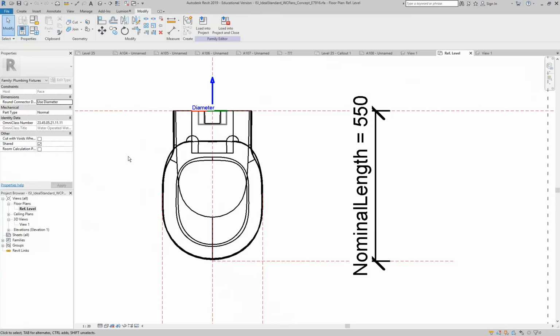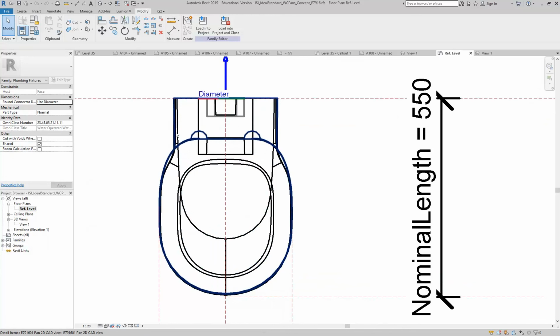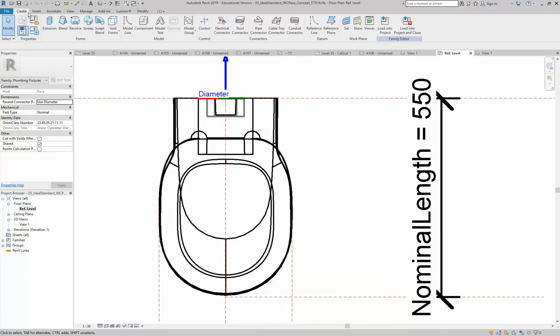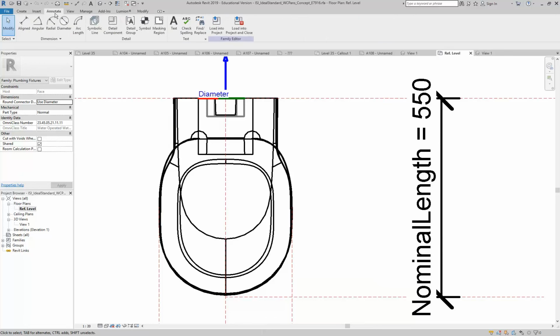This is one of the best things about Revit. It makes it much more powerful in a way than ArchiCAD, because of all the different display options you have. So you've got the option of having these detailing tools to show things in plan or another view that's different to the 3D display. It's on the Annotate tab, same as what I'm going to show in the project in a minute. The only difference is, in a family, you only have